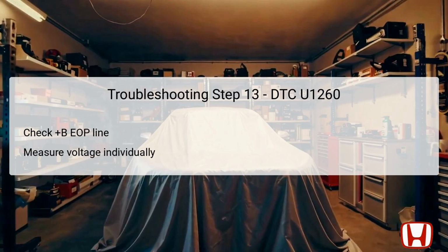Begin by switching the vehicle to on mode while keeping the auxiliary fluid pump relay 4P socket and pump connector disconnected. Measure voltage individually from the designated test points to body ground to confirm whether battery voltage is available. If battery voltage is present at these test points, it suggests that the power circuit feeding the pump is functional.